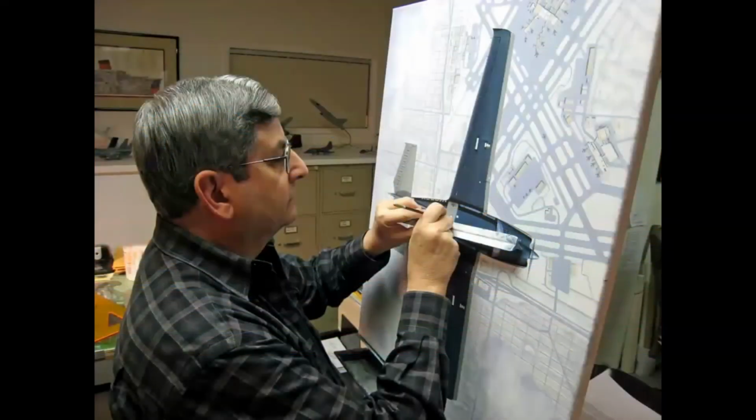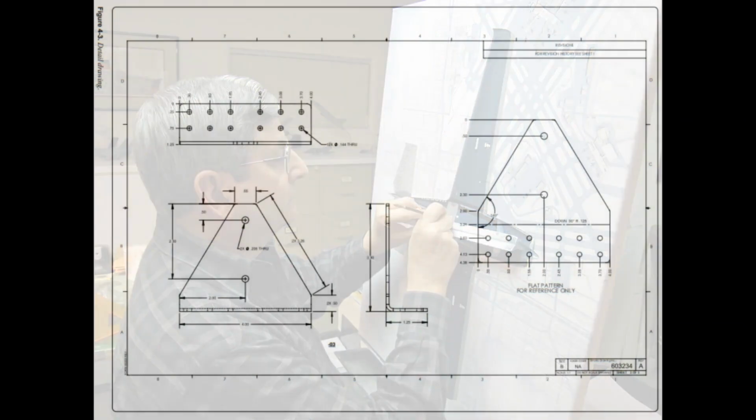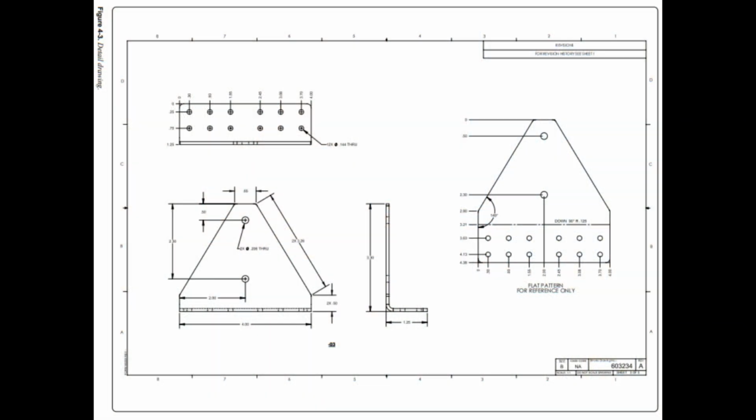Detail drawing. A detail drawing is a description of a single part, describing by lines, notes, and symbols the specifications for size, shape, material, and methods of manufacture to be used in making the part. Detail drawings are usually rather simple. When single parts are small, several detail drawings may be shown on the same sheet or print.